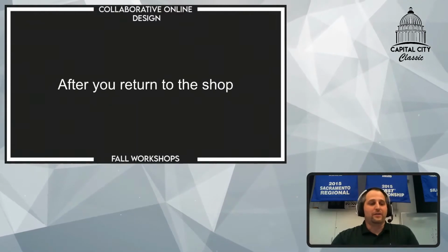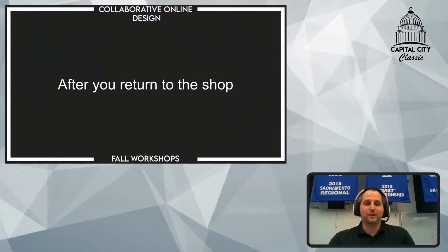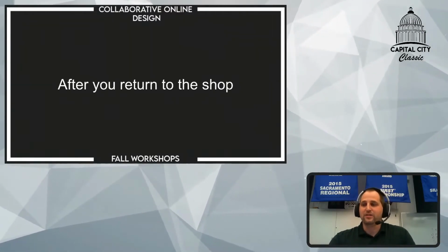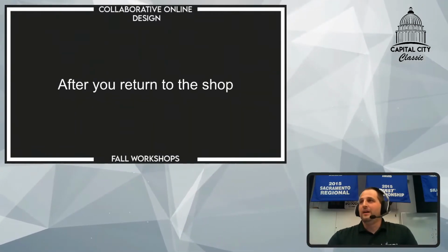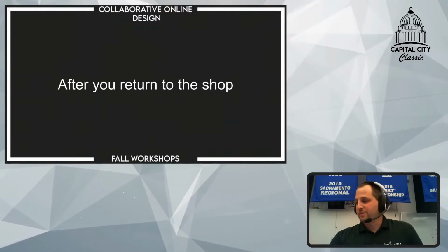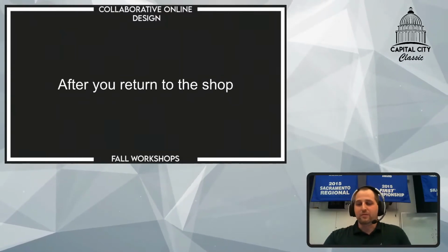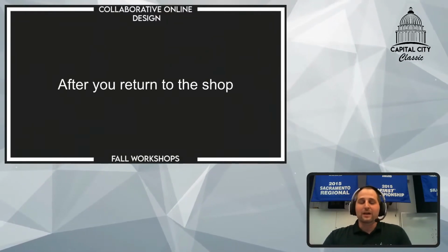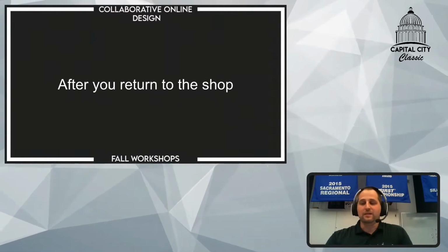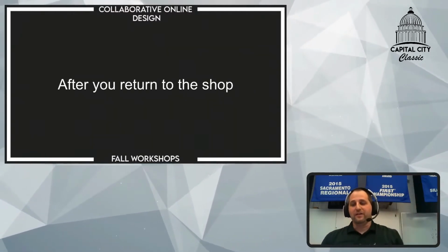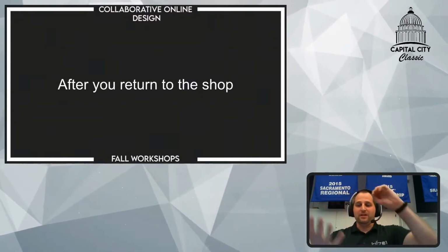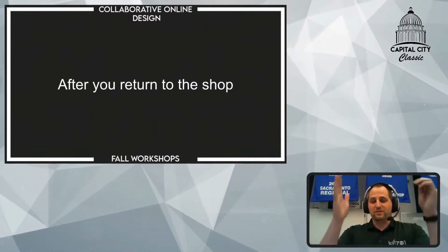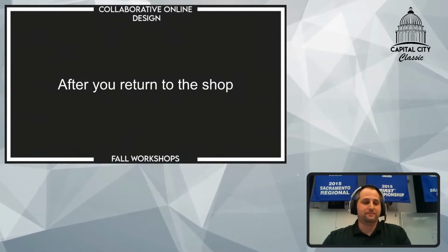What we've found is that we can use a branch in Onshape specifically for the manufacturing team, and they can see this part on their phone or on a computer without hunting someone down. They can hide aspects of it and explode it out on their own to see exactly how it's supposed to go together in 3D space, whereas a drawing is just two-dimensional.